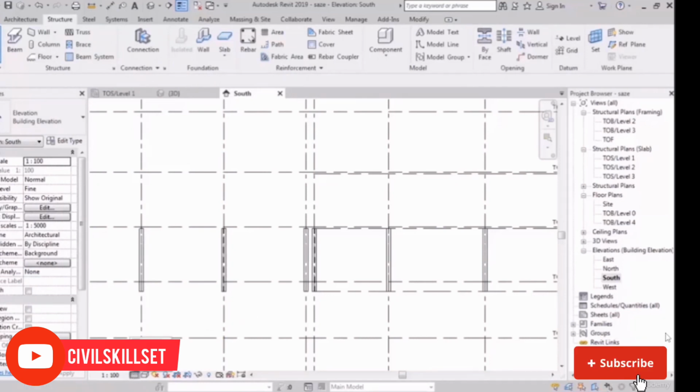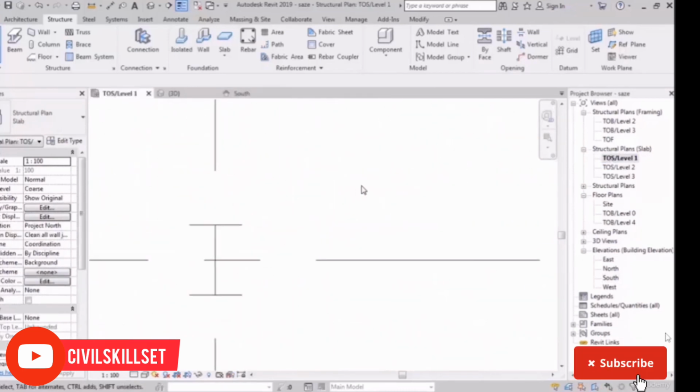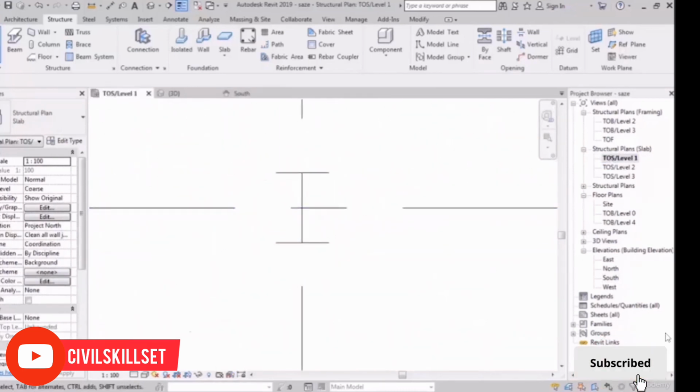So remember that if the detail view is coarse, they will be shown to us as lines. So definitely change it to fine. For example, in the same plan, where we check these columns, they're being seen as lines. So if we change it to fine, we can see the volume too.